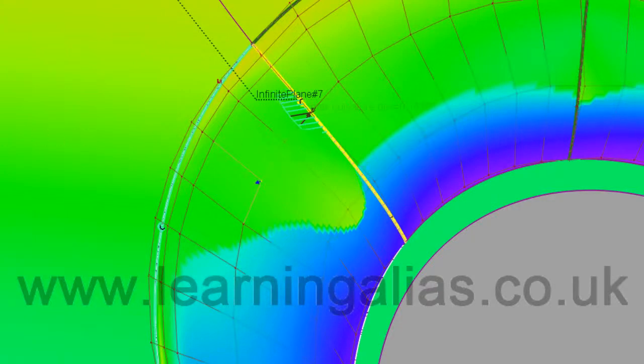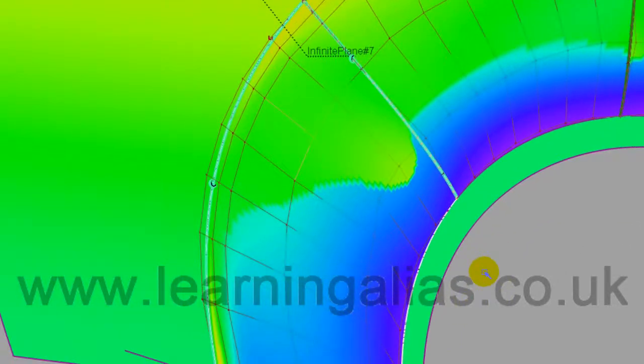There's not much at this level that's resolved by moving one CV. Okay, I'm doing this in real time. Okay, so we've done that, but we've still got this problem which is going to mess up our highlights. So what can it be? Well, the obvious thing is to go to the G3 CV, which is that one.